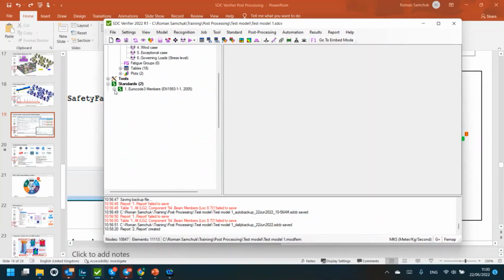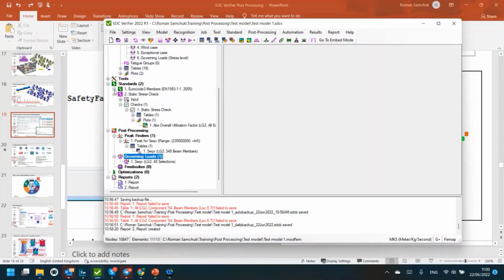So thank you. The main message is that the governing load tool does not solve the project for you. I mean, it does not solve your engineering problem, but it significantly helps you to solve it. Because if you see that something went wrong, I have inordinately high results in my element, it shows you where it came from, and you make the engineering decision. If I see that my member fails due to the bending check, you can find out what is the governing load causing this bending moment in my member, and you can reinforce it in that direction. So this is a nice tool focusing on the governing parameters of your checks.